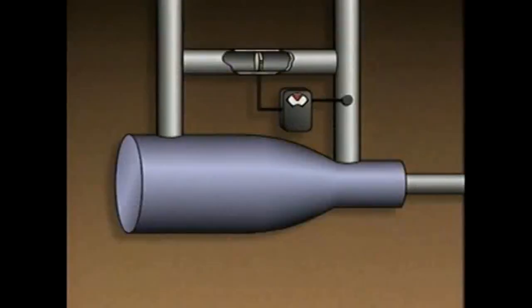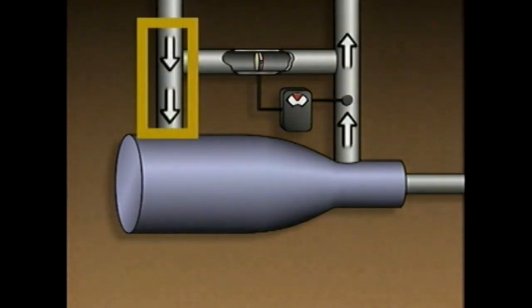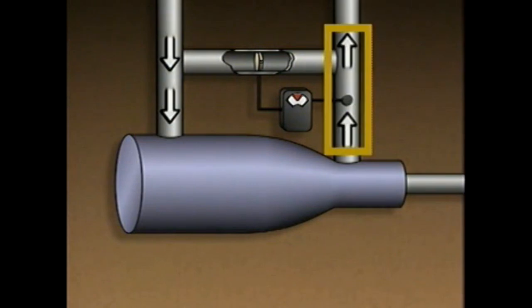One method that is used to maintain this flow rate when the demand is low is to recirculate a portion of the compressor's discharge back through the compressor. This simplified illustration represents an axial compressor with a common type of surge control system. The control system consists of a flow sensor in the compressor's discharge piping, a flow controller, and a recirculation valve that's located in a section of piping between the suction piping and the discharge piping.